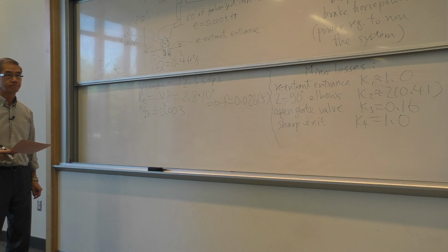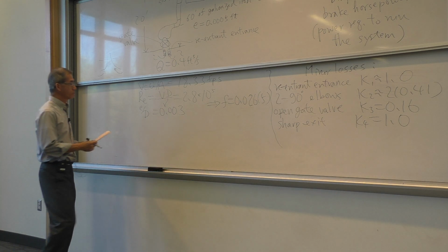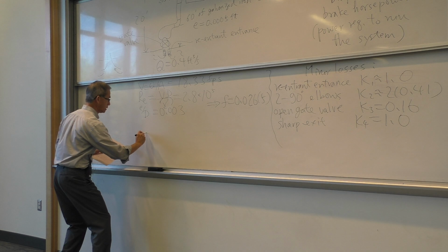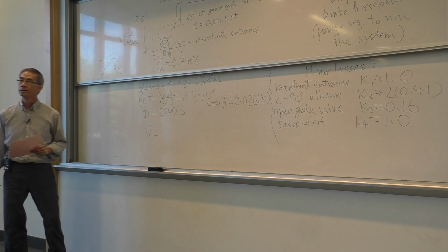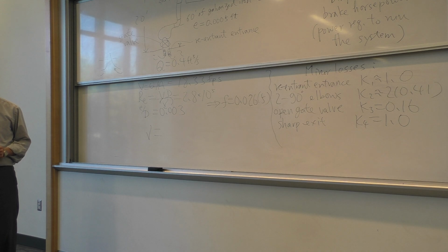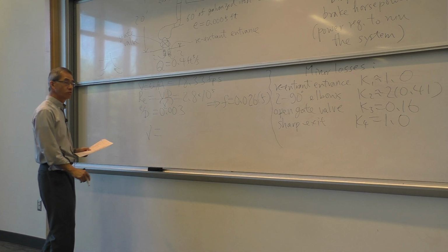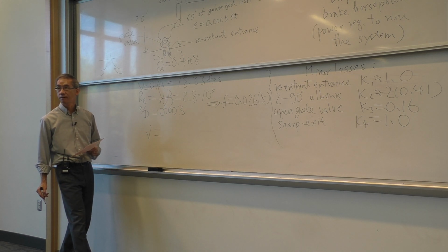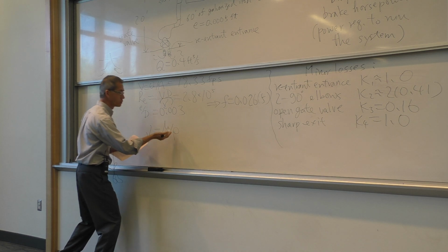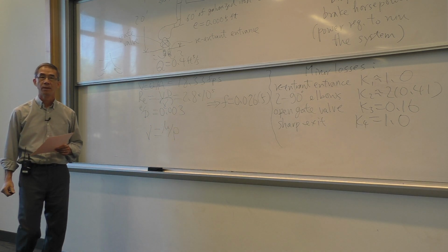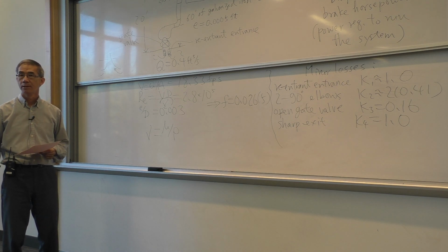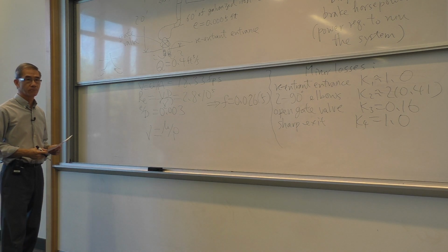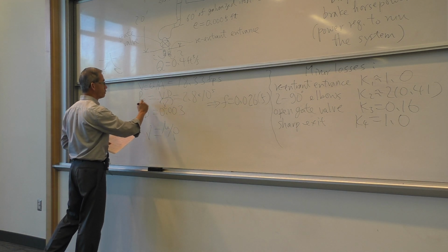Is that the weird-shaped V, the kinematic viscosity, this guy? Yeah, I almost forgot this. So what's this guy? Anyone want to remind me? So it will save you time in calculation in the test, because instead of looking up viscosity and then the density, what is kinematic? Yeah, how is it defined? In reference to the viscosity? Mu over rho. So just a very convenient fluid property that's given also in the appendix, in addition to the viscosity. So it just saves you a step. So at times, this is more convenient.